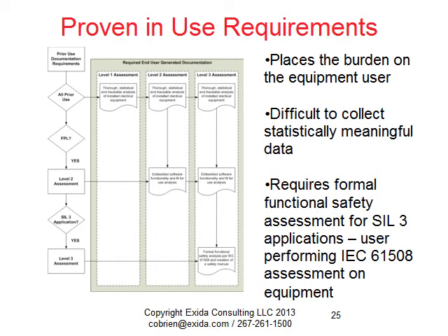And we'll get to some examples of how even a small software change can cause a problem in a few slides. But this means it's the exact same hardware and it's the exact same software, and enough have been installed and run and used and tested over a period of time to demonstrate the robustness of the product for SIL applications.